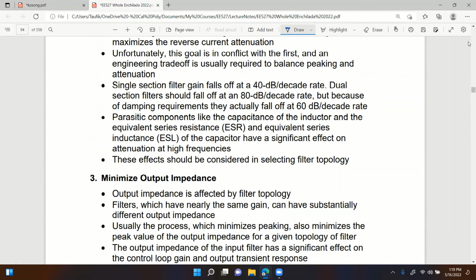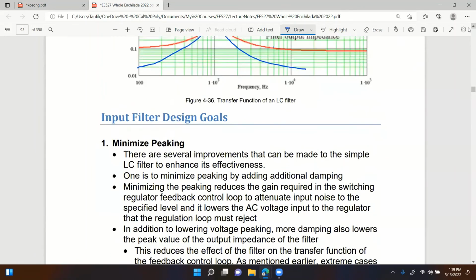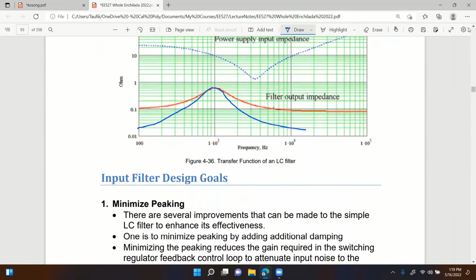Yeah, and then also it has to do with the slope. I forgot. Well, in fact, by doing this, I actually did increase the slope, right? So instead of a first order system, you can do a second order system, third order system, right? Like this. But notice the Q gets higher if you do that, right? So just make sure that when you do this, there's always a trade-off, right? Increasing the order while keeping the same peak would make Q get higher and higher, right?